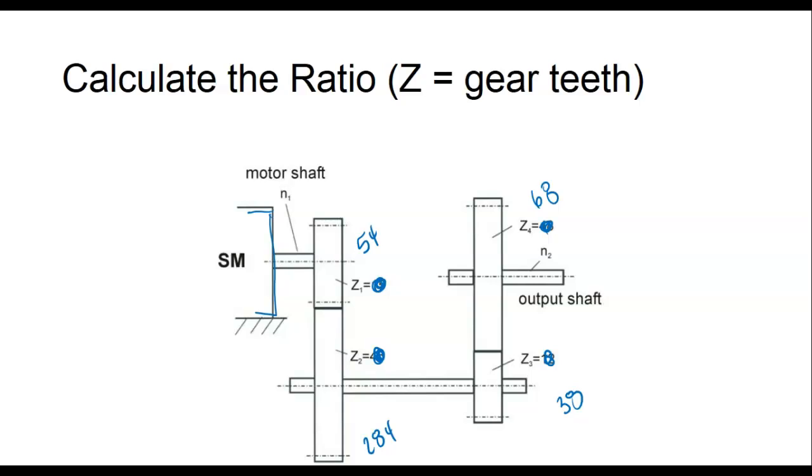But when we're doing our gains, we're calculating torque, because I don't know the speed. I do know the torque. I have no idea what speed this motor's running. This might be a variable speed motor, so I can't say it's got this. All I know is whatever that torque puts out, it's going to give me either more torque out or less torque out than I'm putting in.